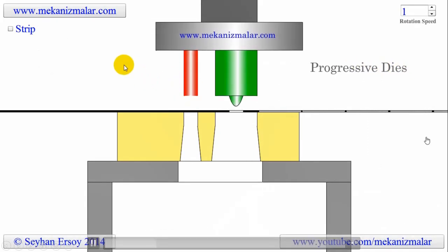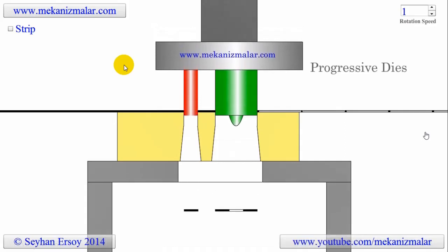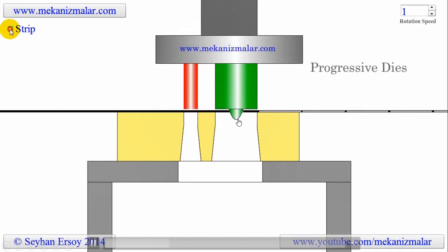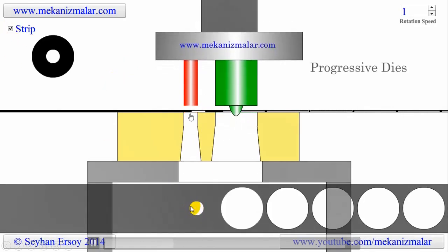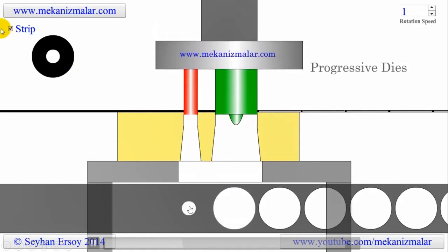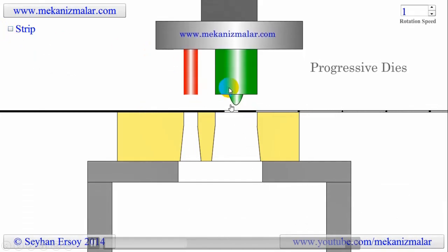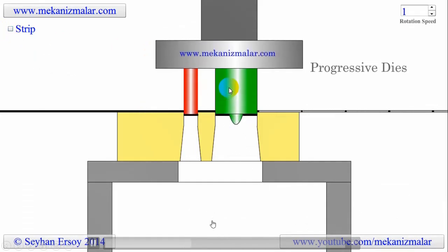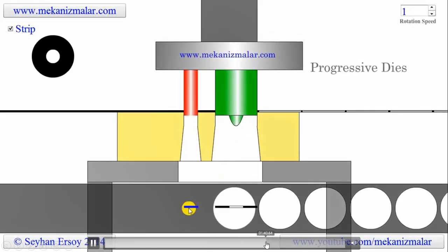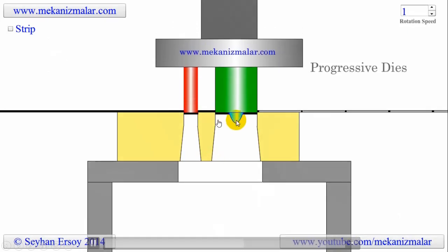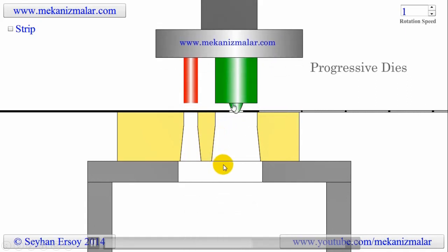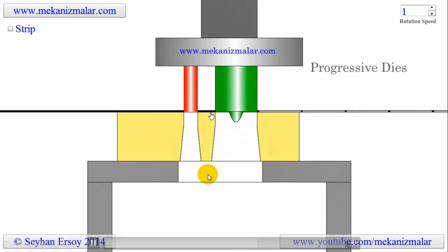See here, this is a punching operation, then after this will be your blanking operation. This is punching, and at that station the blanking operation will be performed. The hole will be created here, that hole will be forwarded, and then your component will be manufactured over there. This portion and this shape is made purposefully to insert that particular part inside the punched hole.